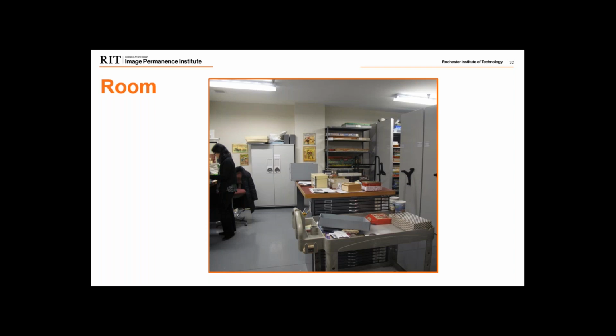And accounting for the human occupancy means that we have to make human comfort a factor, which means we can't do cool temperatures. As long as that person is working in that space, we'd have to use, coolest I would say would be about 65, but typically 68 to 72 degrees. Removing a staff member from a collection space, having the collection space dedicated to collections, is very important to being able to provide a cooler environment.